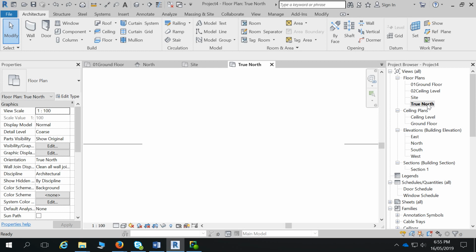So when you get down to doing perspectives and shadow diagrams and things like that, you can actually specify the location as like, TAFE here, whatever the address is, and it'll actually show the shadows based on what they actually are here. So I tend to always try and check Google Maps to see if they've got a timestamp on their aerial shot, just to make sure the shadows line up with about what you think they should, just in case. But it's pretty good.